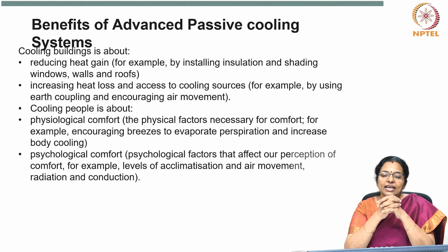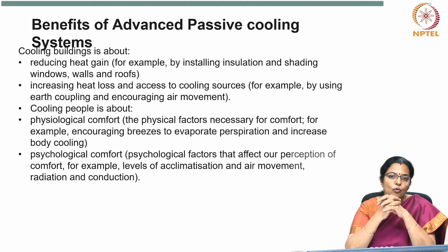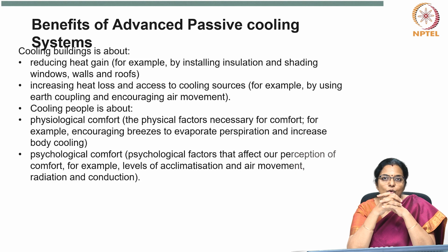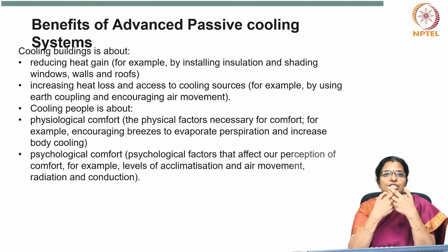With careful design for passive cooling, we can keep the home more comfortable and cool with reduced energy costs. So, cooling a building is about reducing the heat gain, for example, by installing insulation and shading windows, walls and roofs, and increasing heat loss and access to cooling sources, for example, by using earth coupling or encouraging air movement.